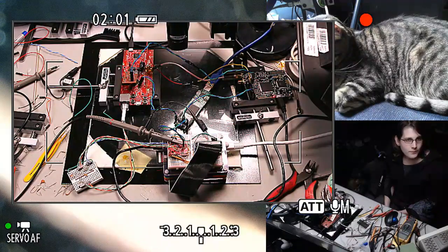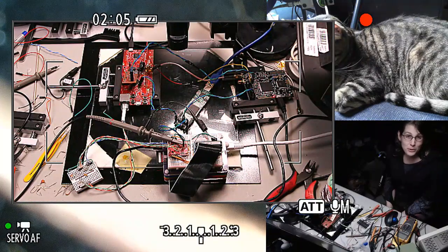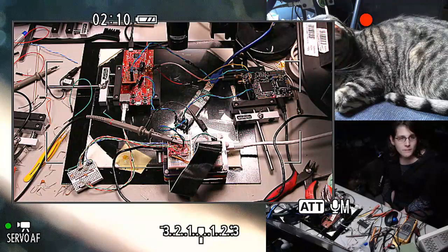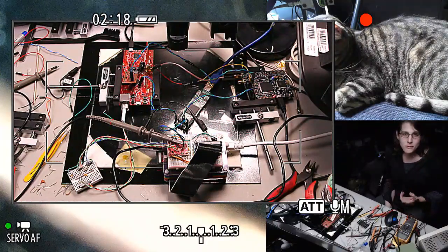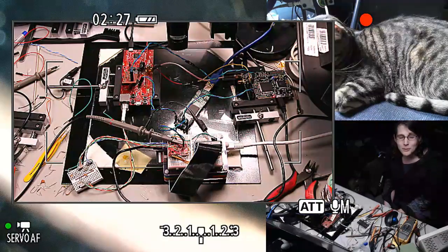So, most of the underclocks I've tried that go below 30 megahertz have started hitting other problems. My first intuition was that it was probably related to the AC coupling, and that the pulses going through the pulse transformer just weren't retaining enough of that sharp edge to still be read as a 1 or a 0, or some other kind of analog issue with the impedance of the pulse transformer was causing the data to stop coming through clearly once I went below.